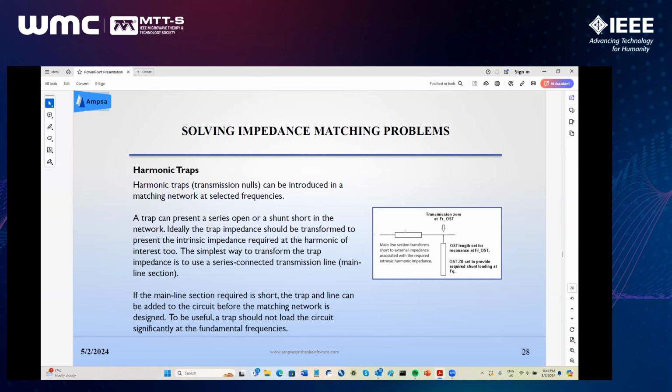So I need a line section. When I have this trap here, the impedance is defined. Now it could be a short trap, or it could be an open trap. That doesn't matter, so it's my choice. But as a rule, it would be shorter because that's easier to implement in microstrip. But I could make a parallel trap with a lumped component with parasitics.